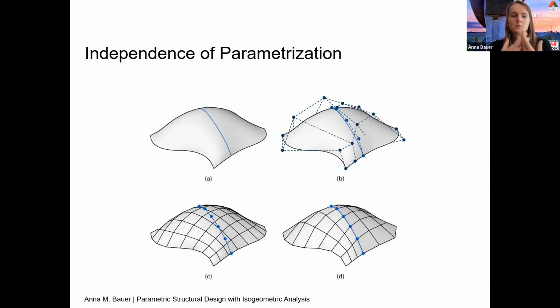If I would have to measure it for classical finite element analysis, I already would have to think about this coupling in between the surface and the curve when I generate my mesh. So there, it's not possible to just generate the mesh for the curve, so the polygon for the curve, and the surface separately or independently, but I have already to know, okay, they have to work together and they have to share the nodes in order to be able to couple them. In isogeometric analysis, I can just use weak coupling without matching discretization, but with matching geometry.